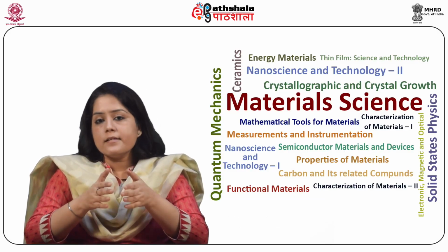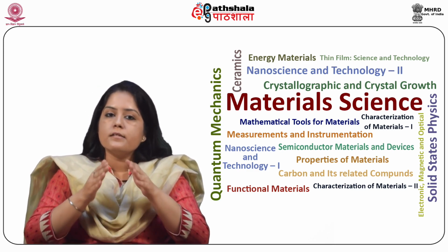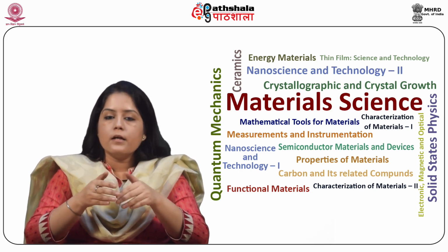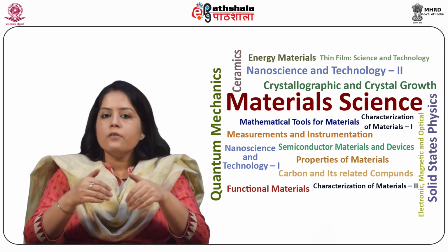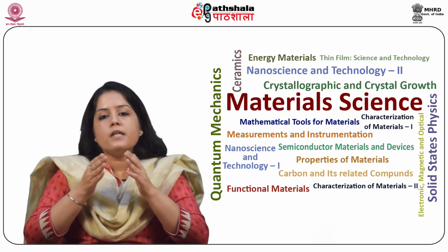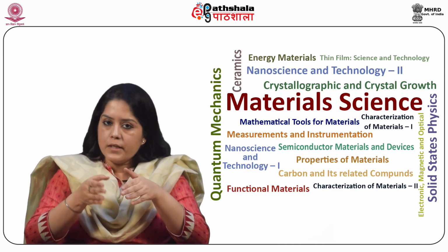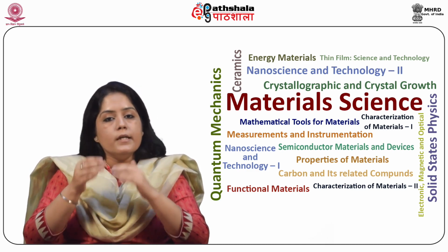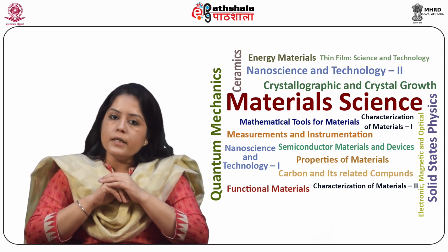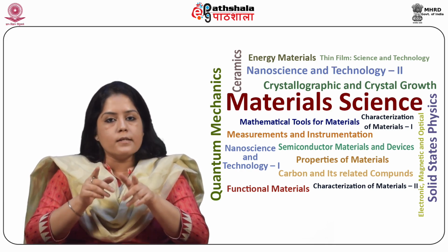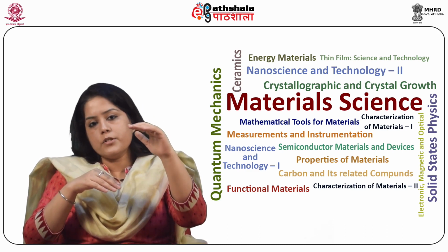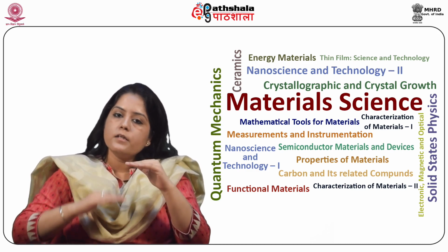So students, let us summarize what we have learned in this module. The materials exhibiting the shape memory effect are shape memory alloys which regain their shape when they are deformed. Secondly, nickel titanium alloys, copper zinc aluminium, and copper aluminium nickel alloys are the commercially available shape memory alloys. Thirdly, the shape memory alloys exist in two different states, that is, austenite phase at higher temperature and martensite phase at lower temperature.